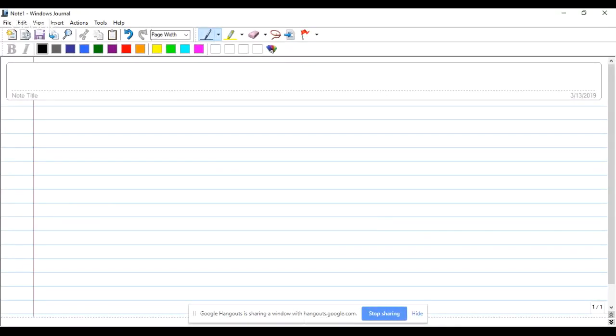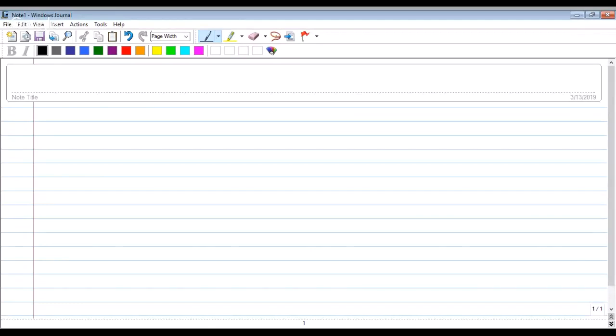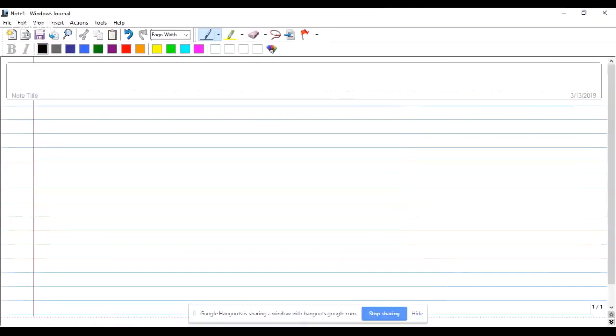So the question was, why do we use a material like, say, gallium arsenide for LEDs, while silicon is used for most other materials? For optical properties, we need something called a direct bandgap. We normally represent this by something called an E-K diagram, where E is the energy, along the y-axis, and K is the wave vector. We normally take the reference to be the top of the valence band. You remember reading all the assignments, everything is with respect to the top of the valence band.